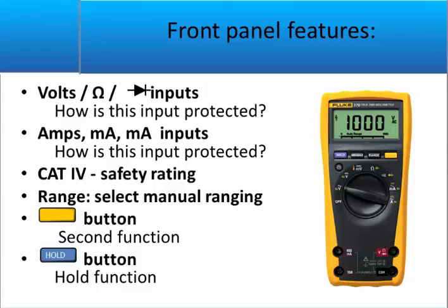A lot of different styles of meters do have a fixed range, and you can select those by the rotary dial generally, or some of them may also have auto ranging. In other words, they look at the reading you currently have and the range of the system, and then put that into a range, the dynamic characteristics, to best suit the inputs.